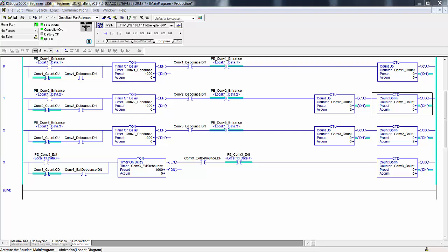Now, it's unlikely that you would run just conveyor 2 and not conveyor 1 to pull a carton onto conveyor 2, because there may be enough friction between the bottom of the carton and conveyor 1 that you can't extricate that first carton from conveyor 1 onto conveyor 2. Then in step 8, carton is at the entrance to conveyors 1 and 2. Decision is to run conveyors 1 and 2 or to wait for logical conditions.